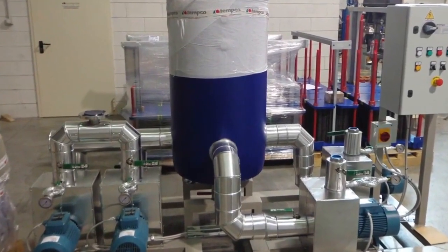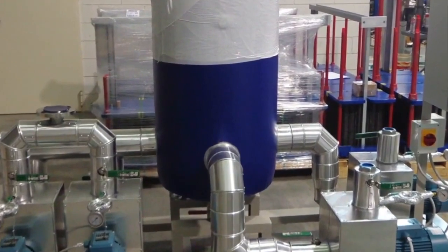Let's assume we have water from a fridge unit arriving at 7 degrees. Fridges typically operate with a temperature difference of 5 degrees, discussed in a previous video. Water from the refrigeration unit enters the heat exchanger at 7 degrees, and returns to the refrigeration unit at 12 degrees. On the secondary, we aim to cool the processed water as much as possible. What is the limit? If we use a plate heat exchanger, the limit is 3 degrees with a log mean temperature difference of 2 degrees.